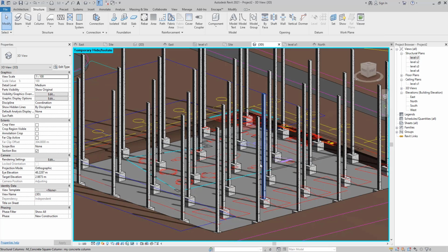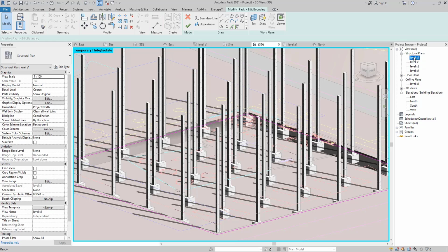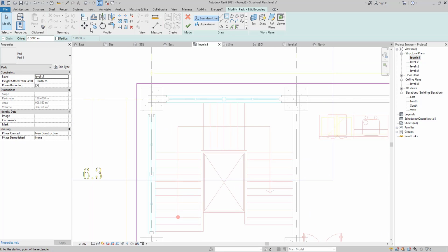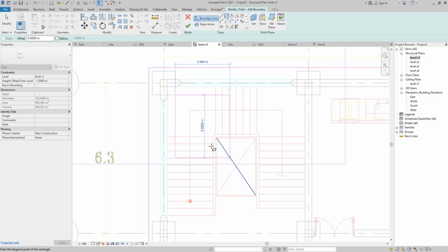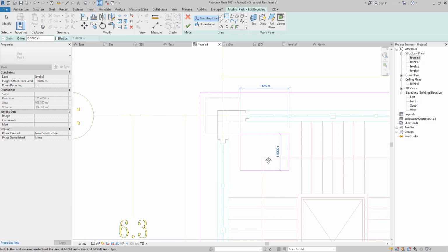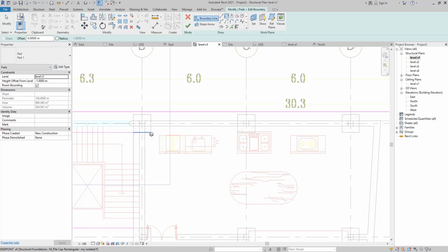Now let's first go to fix our building path by clicking your building path and edit boundary. Let's go to, for example, any level, it's fine. We need to go here, choose rectangle, and choose the offset. We don't even need to choose the offset. We just go and create our rectangle from our isolated foundation endpoint to each other like this.